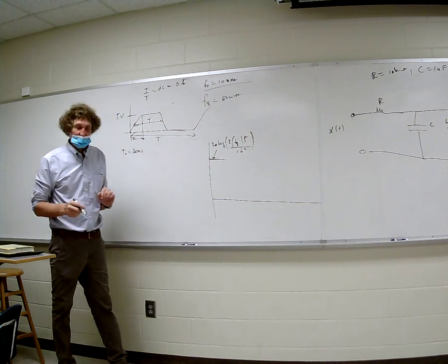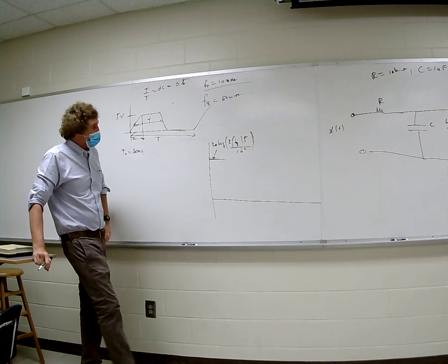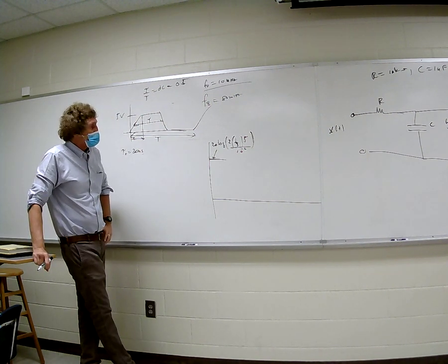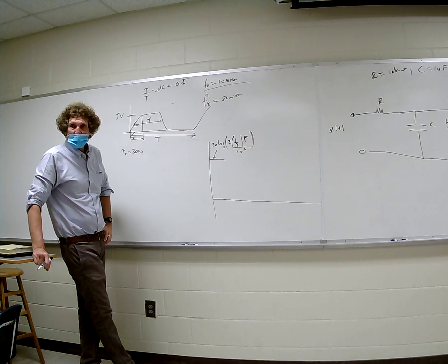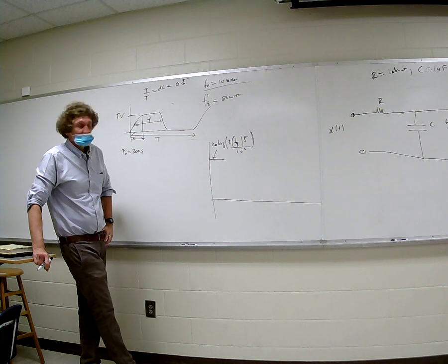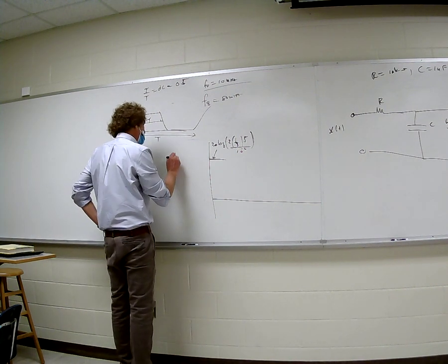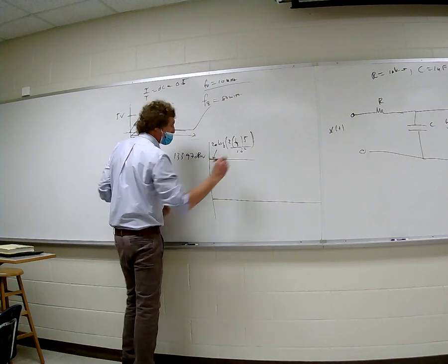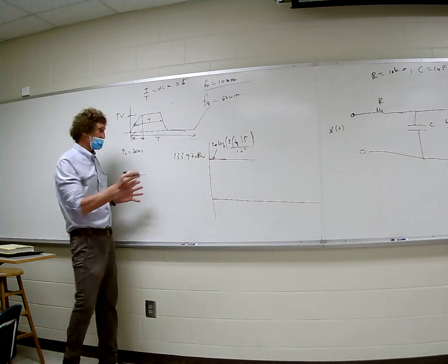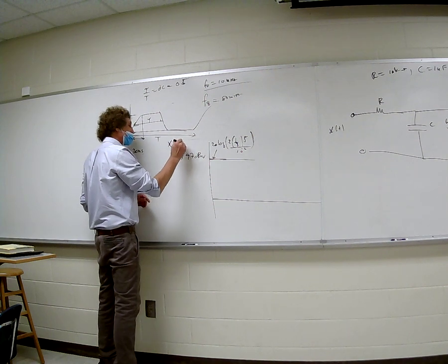Can anybody give me that? It's log of 5 over 10 to the minus 6, 10 to the 6 up top, so it's 120, so it's about 135, 136 dB microvolts, something like that. It's log base 10, by the way. Remember that, not base e. You calculate 133.97. That's about right. 133.97 dB microvolts. That's the level it starts out. This is the input signal.